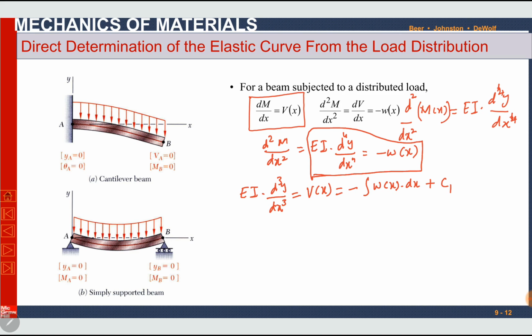This function is also equal to shear force. If we integrate it once more, it will be EI d square y by dx square, which is equal to moment, and the right side will be double integral of load plus C1x plus C2.